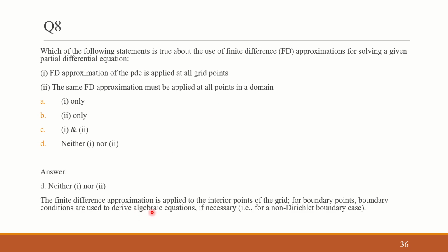The finite difference approximations are applied to the interior grid points. For boundary points, boundary conditions are used to derive the algebraic equations. If it is a direct value specifying the dependent variable, we know the value.